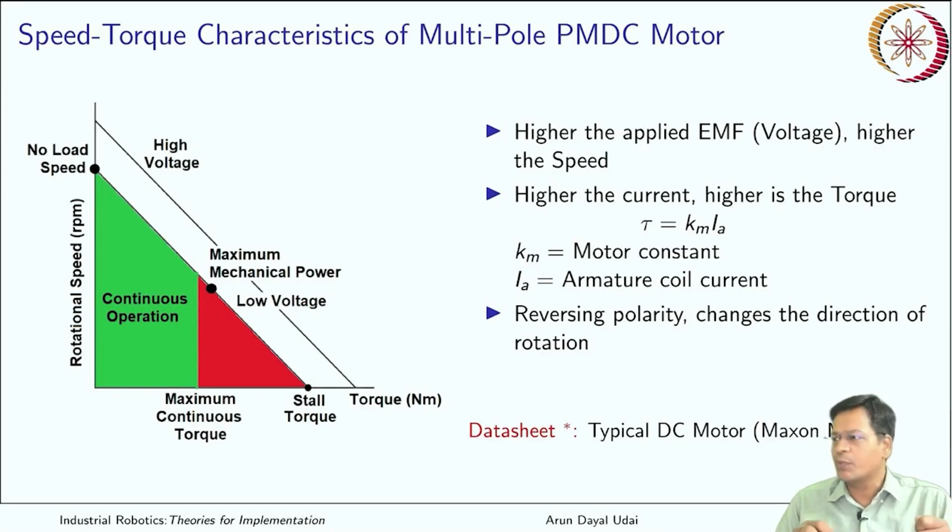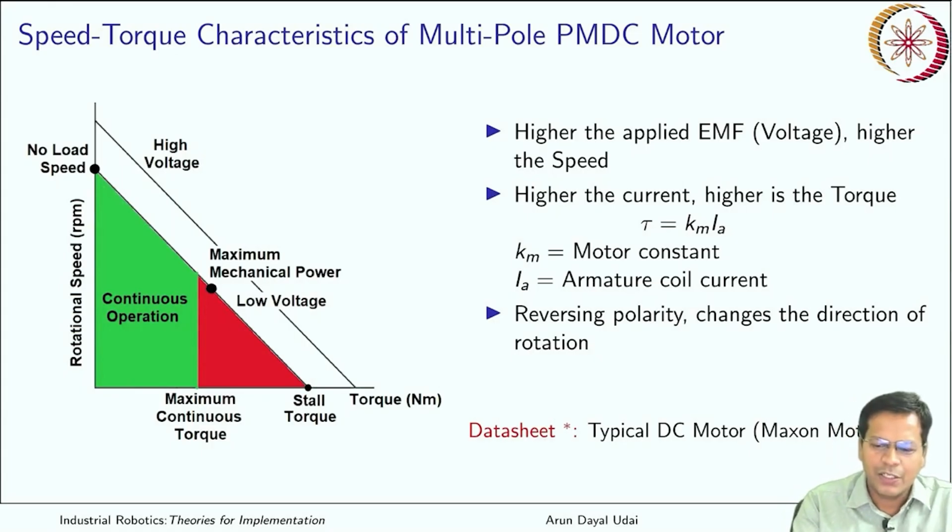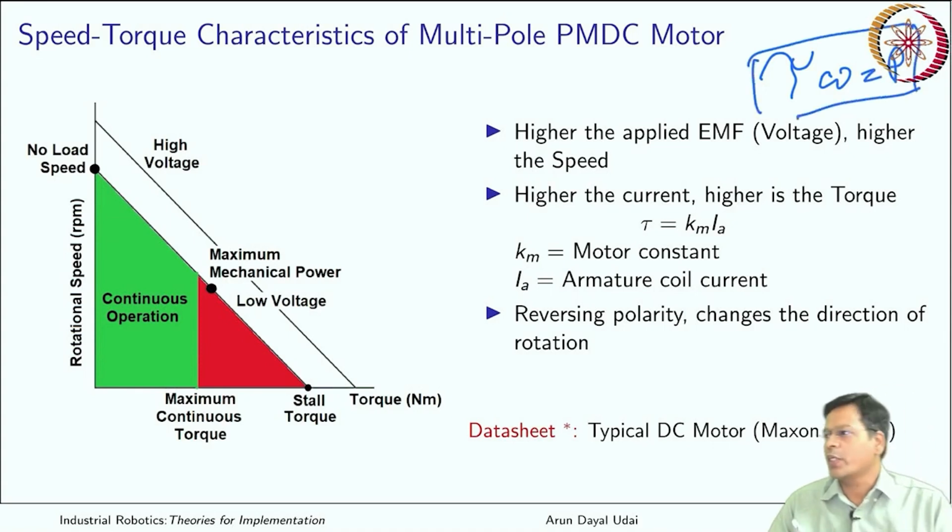One of the very standard equations says torque into omega is the power of a shaft. Because a constant amount of power is fed into this system, if torque increases, angular velocity should decrease.